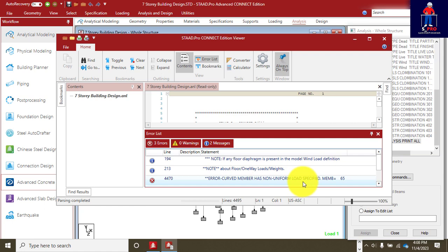If you get your curved beam the way we did, using the curved beam icon in STAAD.Pro, that particular one has limitations. It doesn't accept uniform load, like area load or floor loads on them. They only accept member loads. But when you get your curved beam with normal beams, by creating nodes and you join those nodes to create a curve, it's just a normal beam. It can accept anything. So by next class we're going to modify this structure and fix this error.